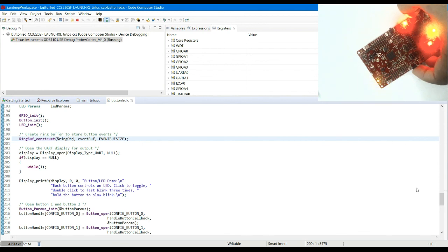Now what I wanted to make you understand is, it is because of the RTOS that even if I place both the systems as long press hold, both the LEDs will keep on blinking, and the middle one will also keep on pulsating. It is because we are triggering multiple events in the callback functions, and they are being managed by the RTOS scheduler.